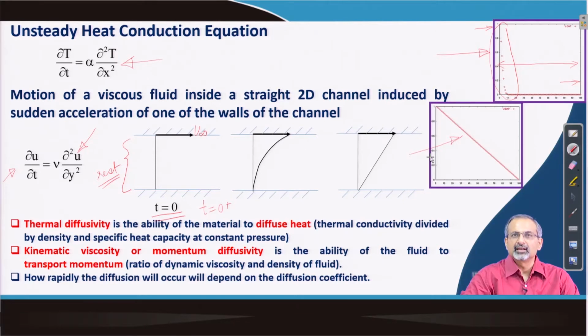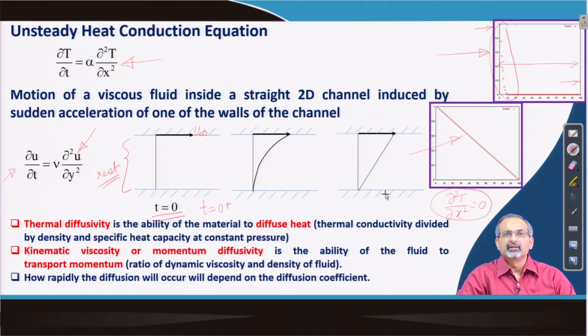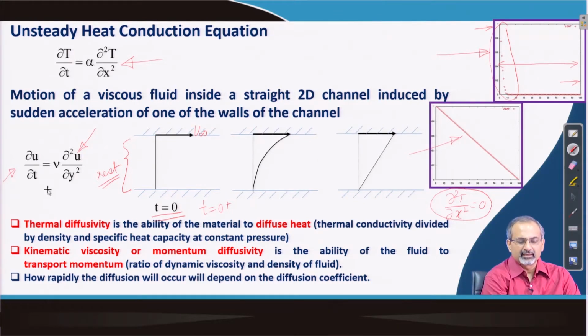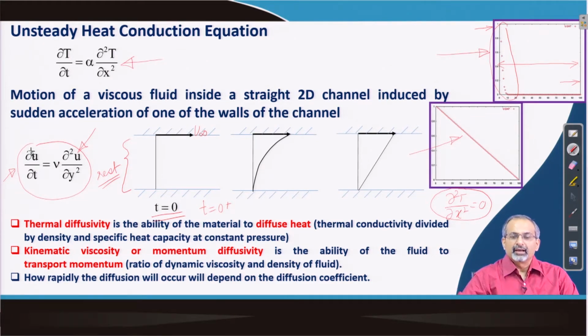And we also discussed that in such a situation, the governing partial differential equation essentially reduces to a Laplace equation when the time derivative term asymptotically limits to 0. So, we can expect that when we model momentum diffusion with the equation here, momentum would diffuse through the gap and we would be able to reach a similar kind of linear distribution of velocity within the gap.